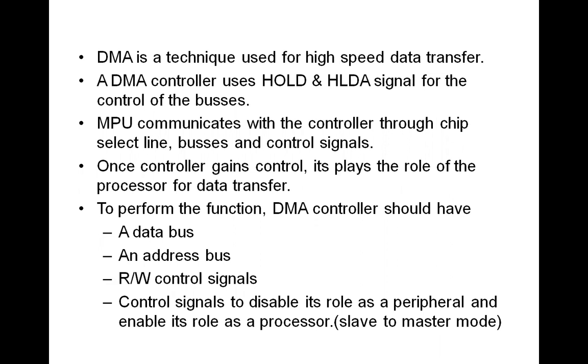And so this is going to take a lot of time, because if it is possible to transfer the data between the devices without any intervention of the microprocessor, then it will be a good way of transferring data. Even though the memory and the input output devices are connected with the common bus, the processor has to come into the picture, because every time it selects the sender device, the source device, reads the information, and then transfers it to the destination device. And if we have to transfer bulk data from one place to another, this process becomes very slow.